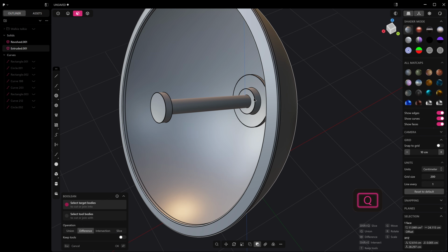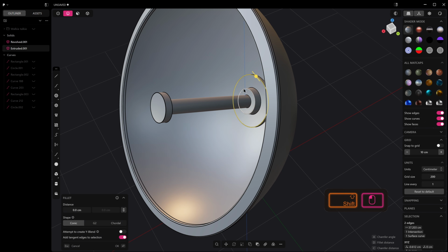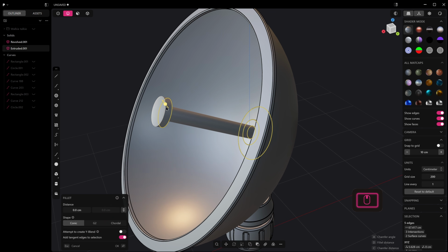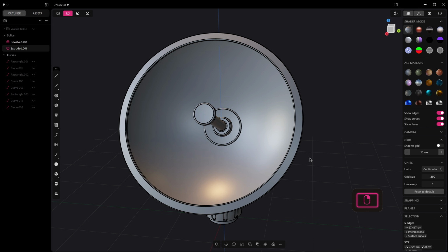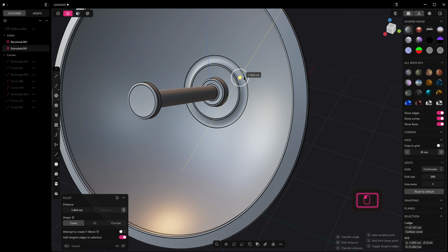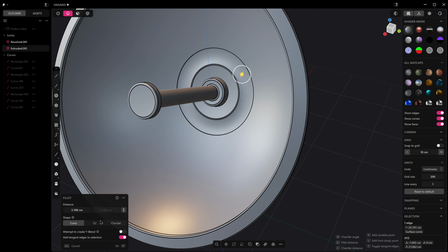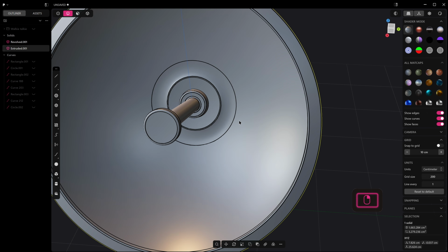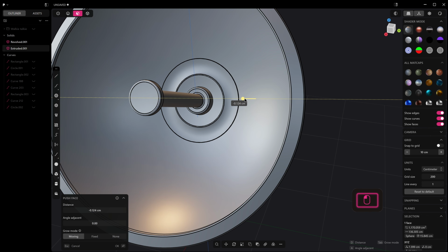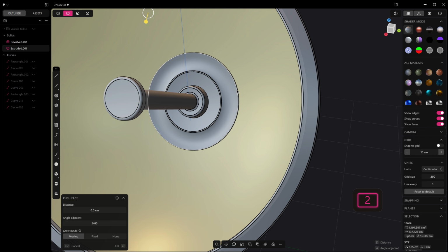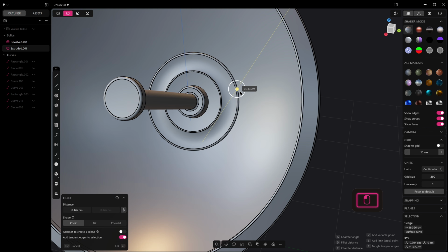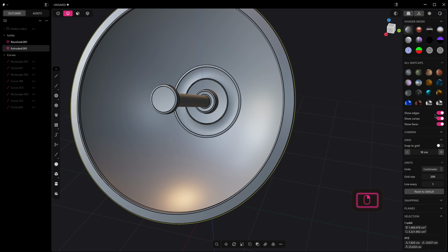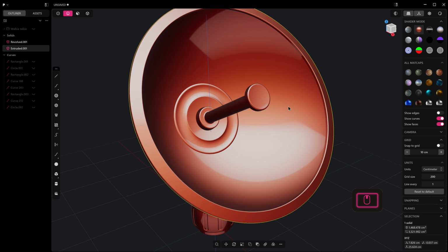We can just add fillets to everywhere that we feel is pertinent, which, for me on this, is pretty much everything except that underside. Okay, and I'm going to call them G2s in this case. And I also want a nice big G2 fillet in the center there. We can maybe even pull that back like that. And that's really nice.